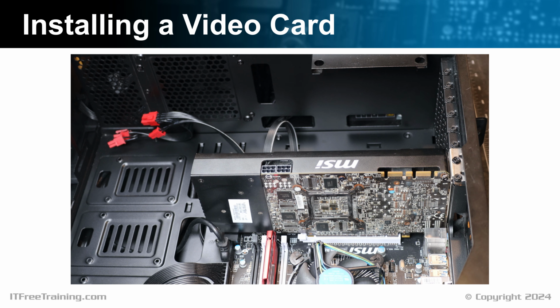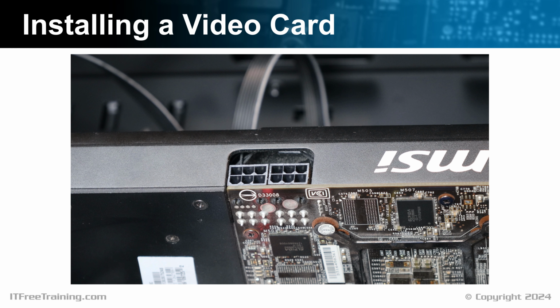In the case of this video card, the video card will draw power from the PCI slot, but this will not be enough to power the video card. To provide extra power, 2 additional power plugs are on the top of the video card. This video card has 2 additional 6-pin power plugs on the top.